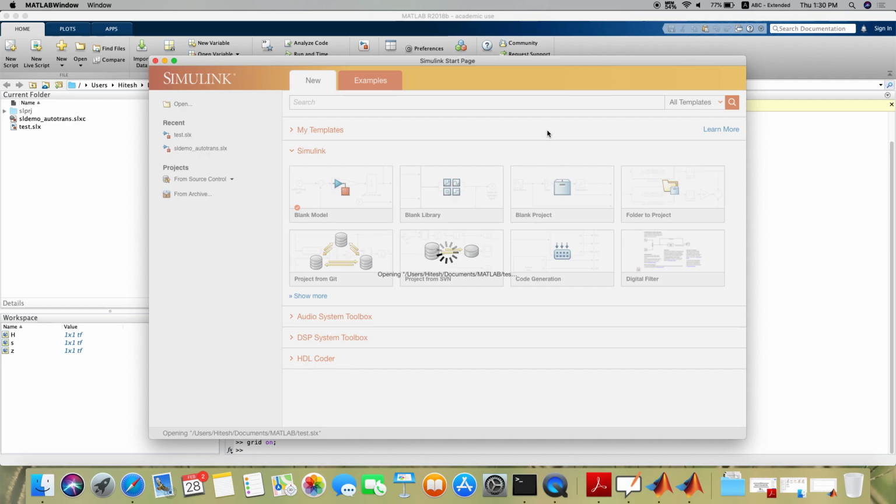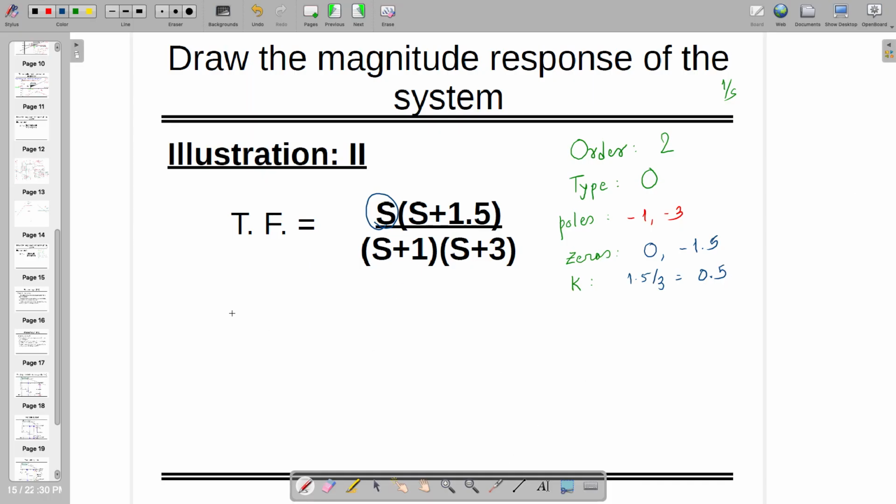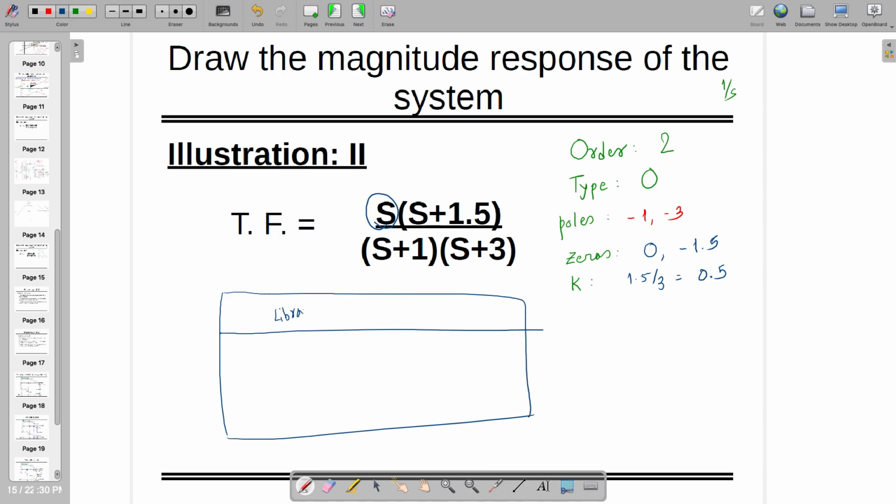So generally, what we are doing in Simulink, Simulink will have a window, and there is a library. When you open the library, there are some ready-made blocks like transfer function. It is known as TFCN. When you double click this, it will open a new window where it will ask where you want to keep the poles, zeros, and small signal gain. Just keep that, and the transfer function is ready. It's the GUI version of what we are doing in MATLAB.